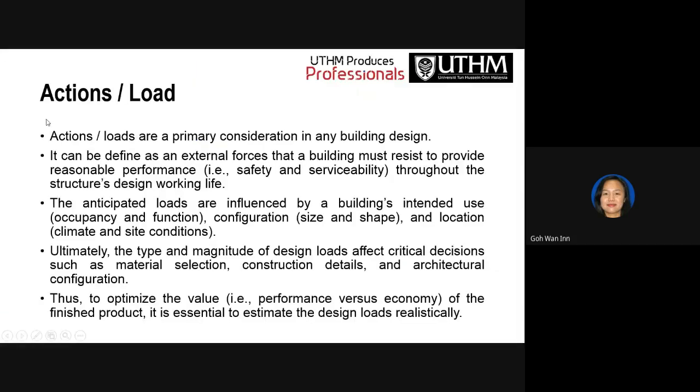So actions and loads are the primary consideration in any building. They can be defined as external forces that a building must resist to provide reasonable performance, safety, and serviceability. You have the load, you remember the SLS and ULS. You need to differentiate that throughout the structure's design working life. The anticipated loads are influenced by the building's intended use: occupancy and functions, configuration, size and shape, location, climate, and site conditions.